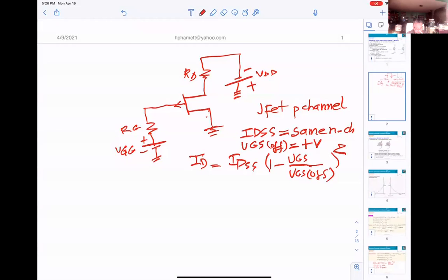Everything we did for the N channel will be the same for the P channel. Only the difference, that's what I bring it up to you. Okay? That's the difference. And also VGS off will be positive, not negative. Okay? So any question about the JFET channel?